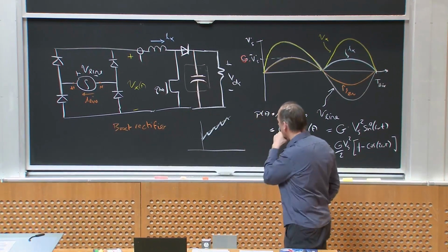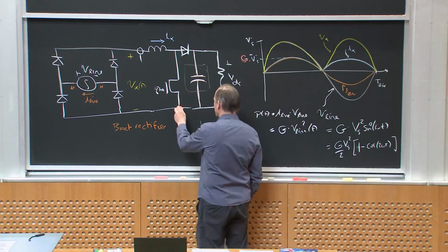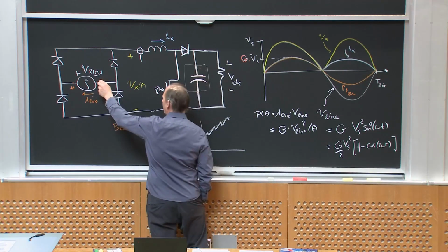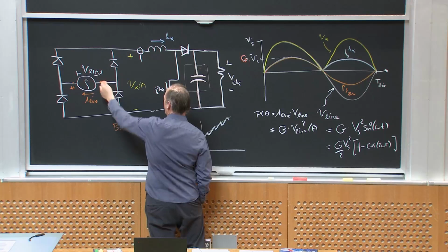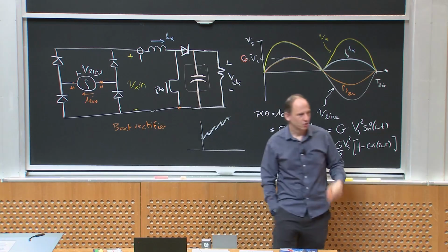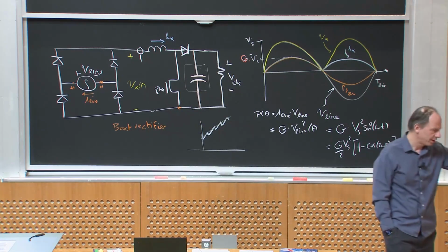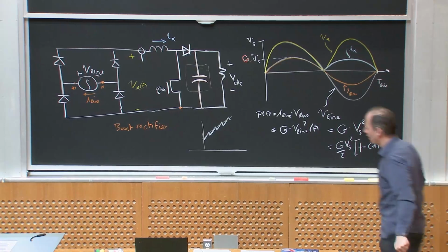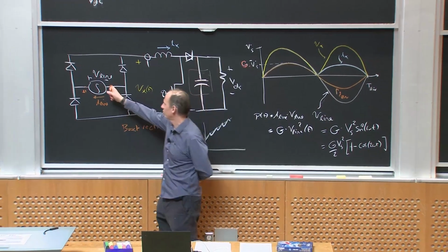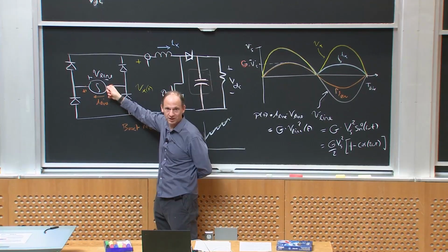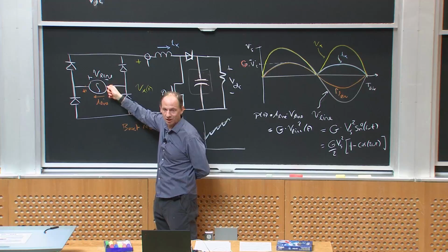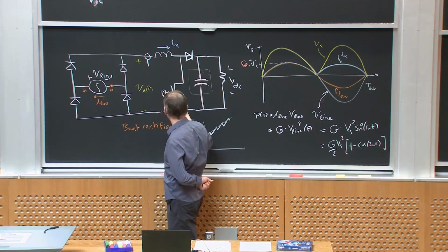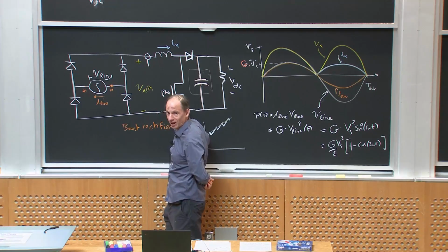Now note one thing, I mentioned this before: this node is nothing like this node, right? These aren't at the same potential. So it's a little bit hard to use, because if I'm plugging into the wall and one of the sides of this thing that I'm plugging into is neutral, that's very close to ground. It's ultimately a DC connected to ground. Yeah, I better not connect this node to ground because bad things will happen.